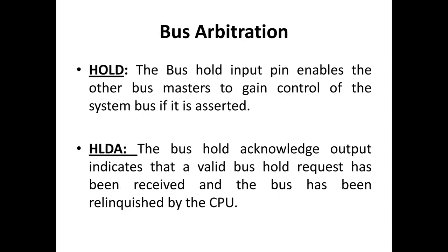Bus arbitration: HOLD pin. The bus hold input pin enables another bus master to gain control of the system bus if it is asserted. HLDA, the bus hold acknowledge output, indicates that a valid bus hold request has been received and the bus has been relinquished by the CPU.